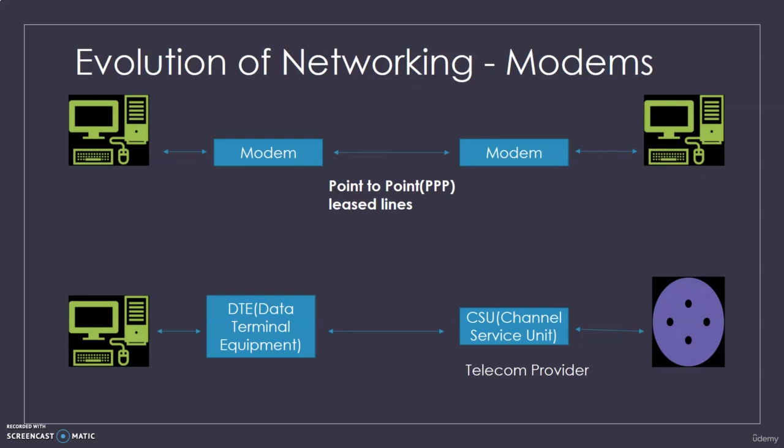This is also a circuit that allows us to communicate not over a crossover cable like we did earlier, which was all digital, but now we can communicate over voice-grade telephony services. That meant we could put in a modulator-demodulator, or modem, so we could convert the digital signal of the desktop into an analog signal over the voice network, and then the modem at the far end converts it back from an analog signal to a digital signal.